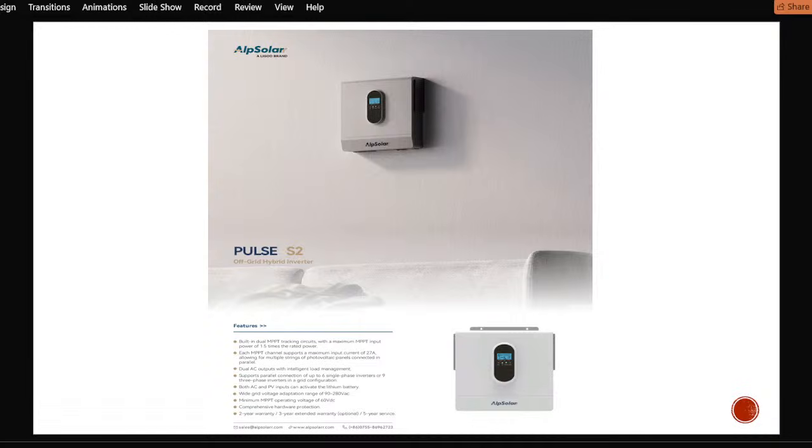Other functionalities still remain the same. Like overload: for 10 seconds, you have 105% to 120% of its capability, which helps in using industrial loads that have surges. It withstands them for that wide range of time until it stabilizes and starts running on its power range.